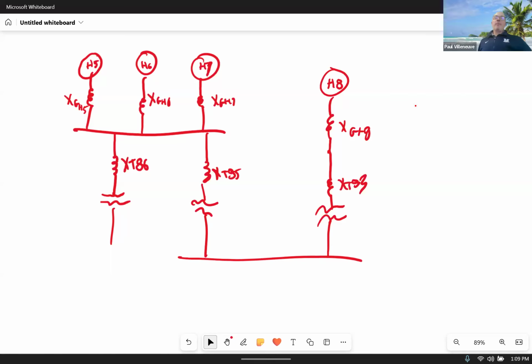So the tripping of the breaker has more to do with the mechanical mechanisms that force the contacts open. But clearly you need beefier equipment if you have to open this bar as opposed to opening this bar. So there's a lot more mechanical stresses and strains, which means you need a lot more mechanical oomph to be able to open those breakers. So that's another reason why with SF6, you can have easier, simpler pieces of equipment.